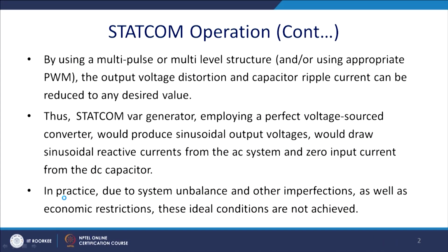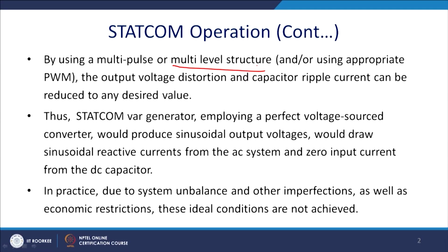By using multiple pulse or multi-level structures, the output voltage distortion and the capacitor current can be reduced to a desired level as prescribed by different standards like IEEE 519 and 514, and it depends on which voltage is connected. There are different voltage levels depending on different regulatory conditions, and that is also a subject of investigation by researchers: what kind of multi-level PWM structure will be more economically suitable for the particular requirement of the Statcom, as well as what kind of PWM technique will be suitable.